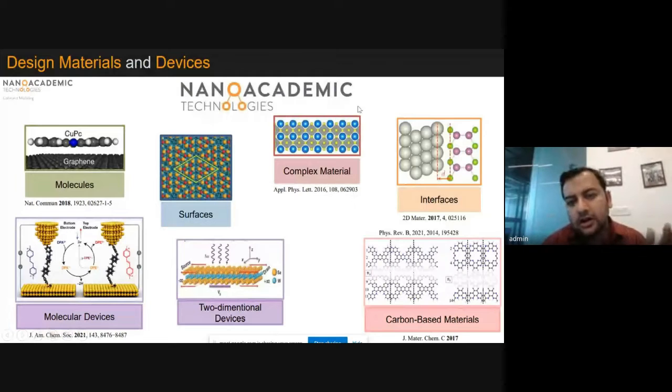You can also simulate nanowires or other applications, including complex materials with tetragonal, hexagonal, triclinic, rhombohedral lattices. Different lattice parameters you can define by yourself, or you can import the material files as well. And for 2D material based devices, if you want to work on graphene based device applications, then definitely it is possible. You can make the graphene sheet, define some electrodes, apply some biasing on the right side or left side, and then you can plot the IV characteristics or photocurrent, photodetector applications, or other material characteristics as well.